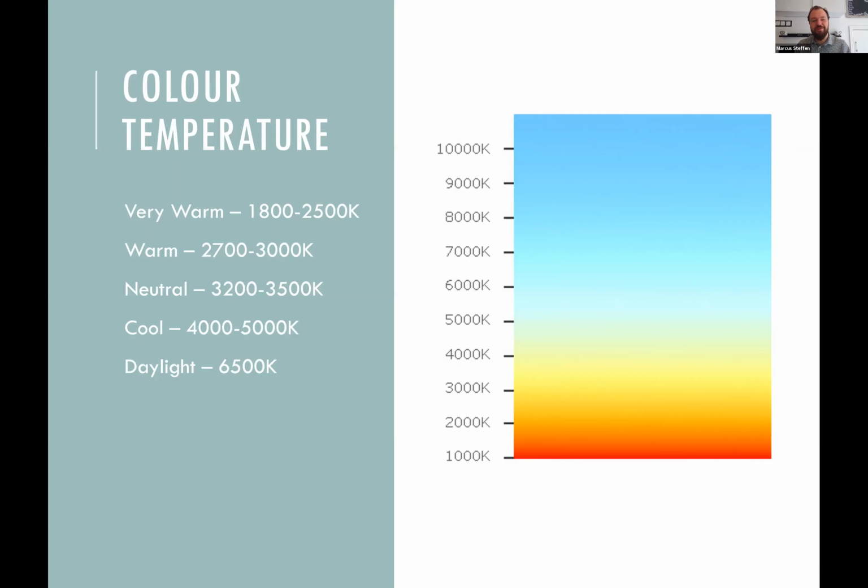Now, when I talk about color temperature with clients, I'm very much looking at the warm white range as 2,700 to 3,000. When we're talking about general lighting, this is residential and hospitality, we're looking at that range there. Now, you can go warmer than that, but what I try to emphasize is that sometimes people will call 3,200, 3,500 warm white, and I don't perceive that as warm white. I don't treat it like that. So when I advise clients, when I advise students who I teach, I'm saying 3,000 or below, that's where you want to be sticking if you're looking for a nice warm white.